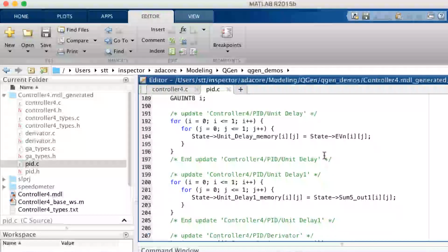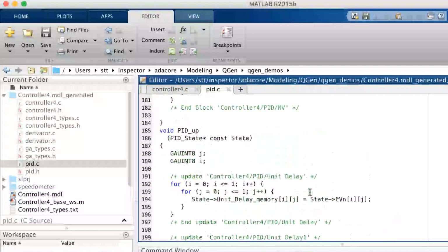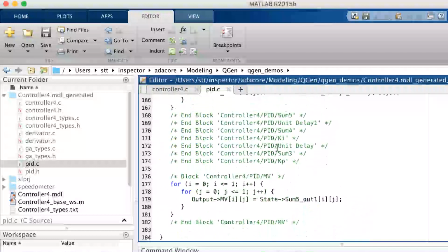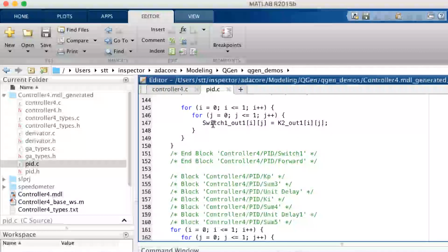It would be calling the nested subsystem, passing it some memory to be updated. The update procedure only manipulates the state, it updates the state, whereas the computation does not update the state, but it uses the state to produce the output values on the output signals.